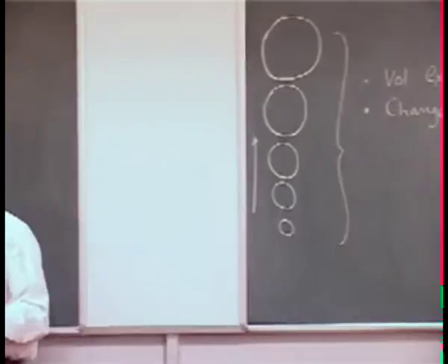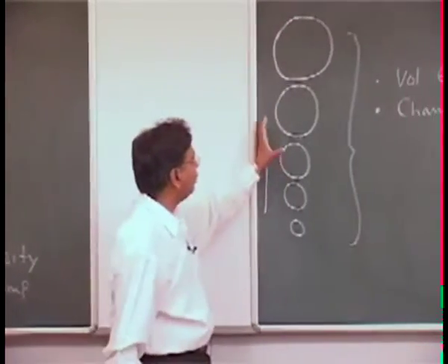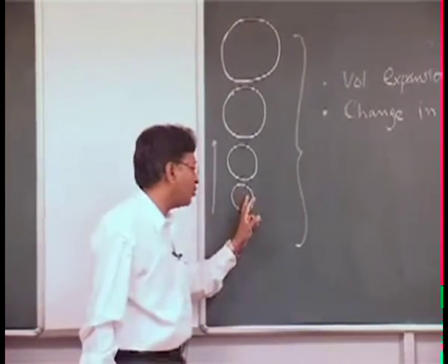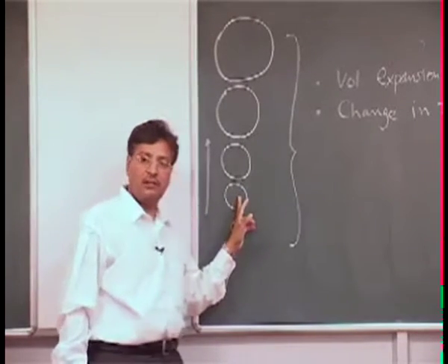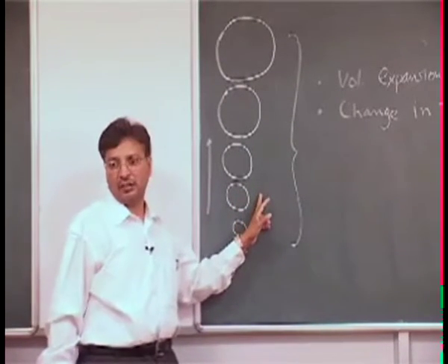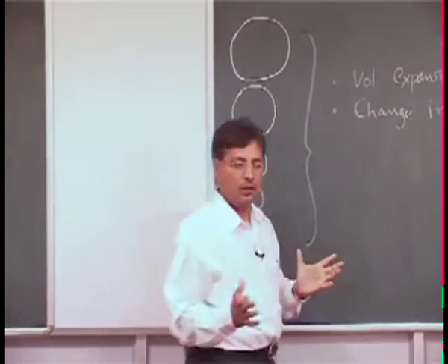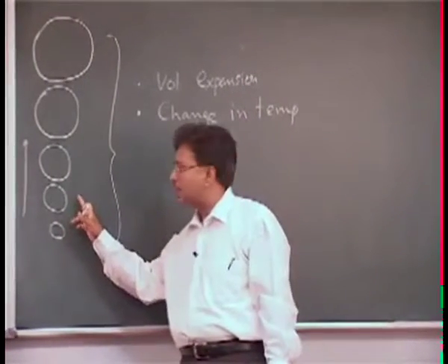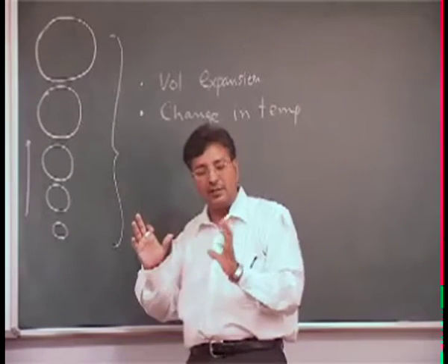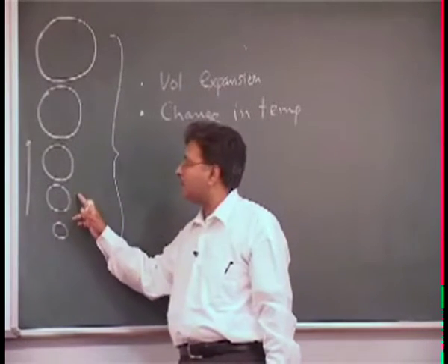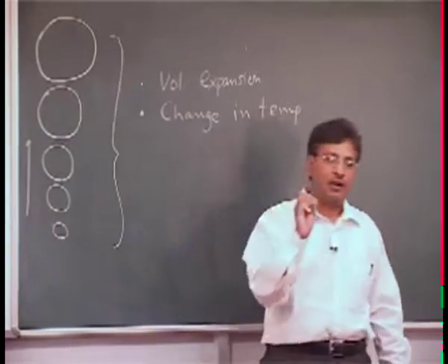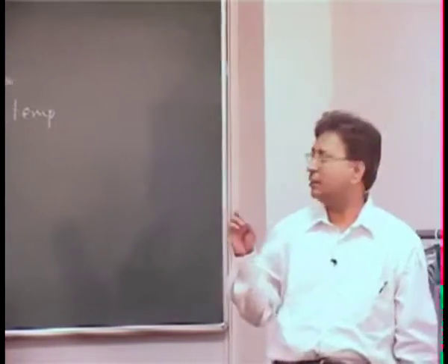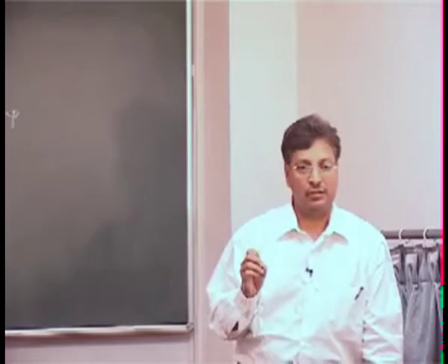Let us make an assumption here that, because of the change in pressure as things are moving up, expansion is taking place, but there is no transfer of heat between the parcel of air that I am considering and its surrounding, which is a reasonable assumption. Things are happening so fast that the heat transfer between the air parcel and the surrounding air is negligible. If you agree, there is no transfer of heat between the parcel of air as it is moving up and the surrounding air. What is such a process called?